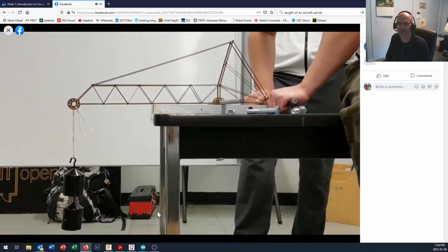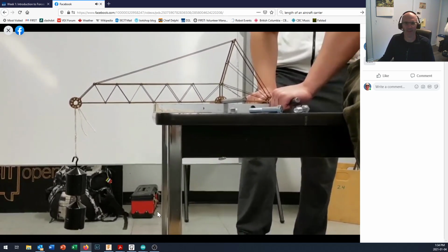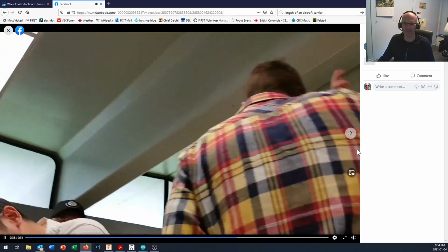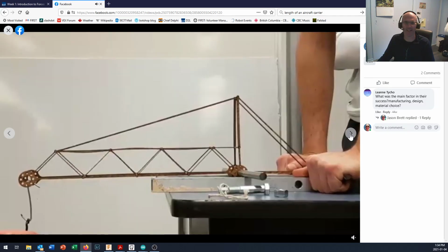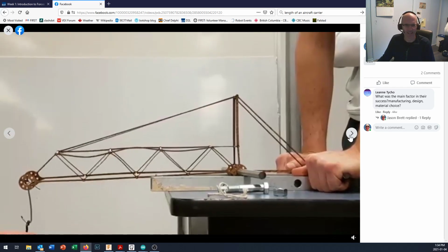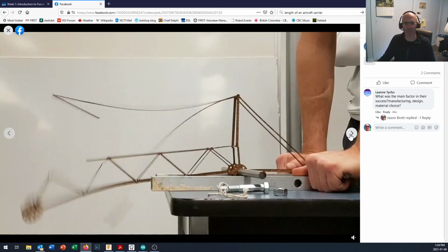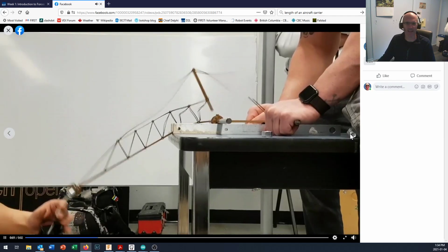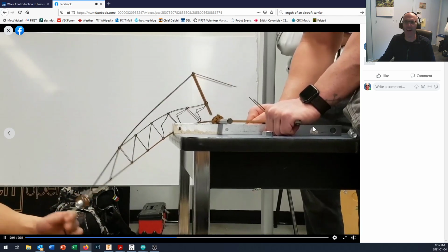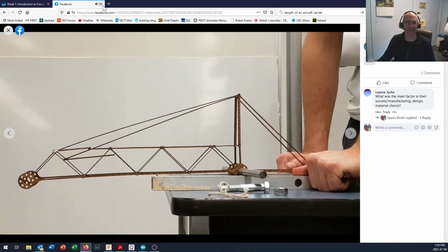Looks like this one is going to meet its needs. Oh, very efficient truss design right there. Here comes another one that wasn't quite so efficient. And you'll notice the mode of failure in there, a lot of buckling in the members. So we'll talk about how that comes about and how we analyze that to see that happen. Oh, there's another one that went. And that must be the last one because it just keeps on repeating. There's a nice one with the buckling on it.